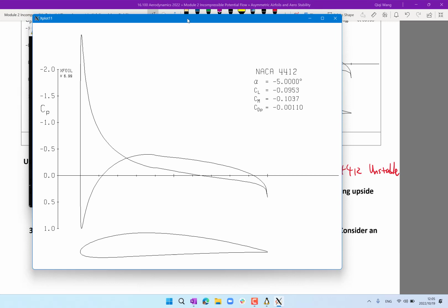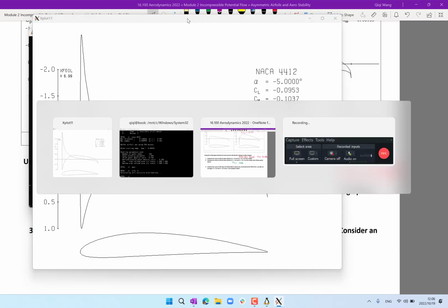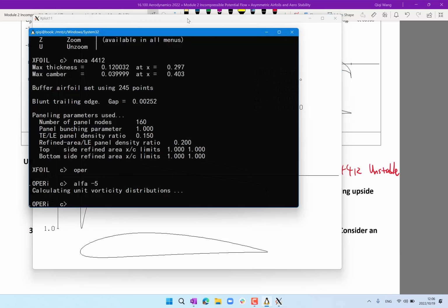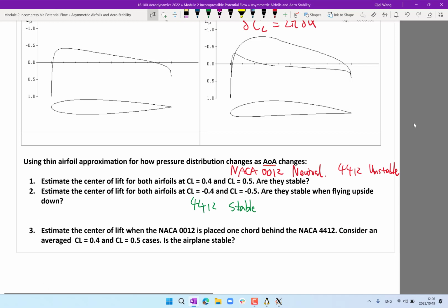You get a very high peak of force downward near the leading edge, right? Remember, the flow comes at a negative angle downward. So you get a downward lift near the leading edge, but the pressure between upper and lower surfaces flips over at this location. So you get a positive lift over here, right? So let me just draw it on the board.